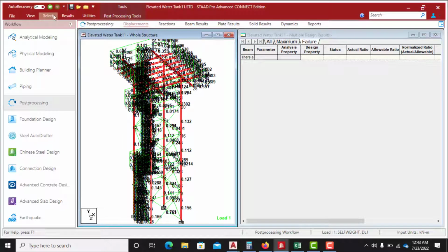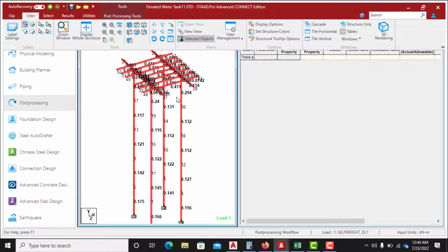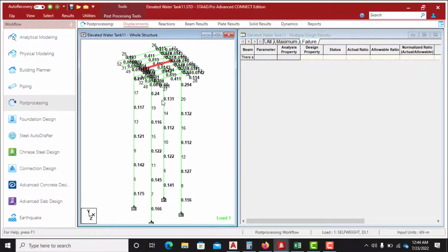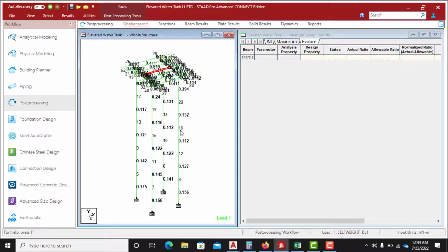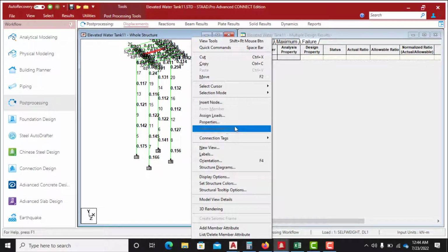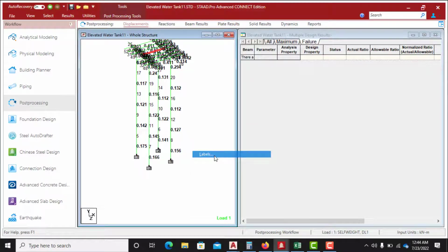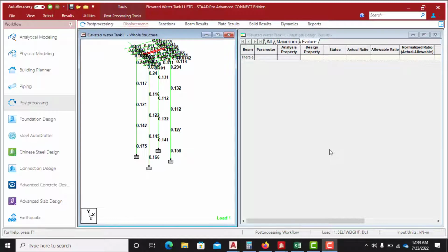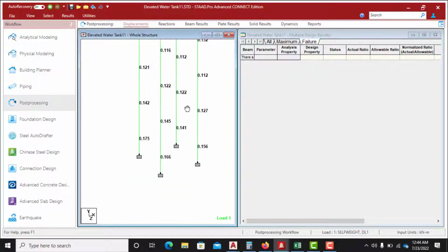Yes, so I will isolate other ones. You see, okay, let me remove my node number, because if you are seeing 69, you think it is the deflection ratio. Let me off my node number. It is scaring anyway. You're not supposed to have any value there up to 1. Good. So you see, my columns are doing well in deflection.